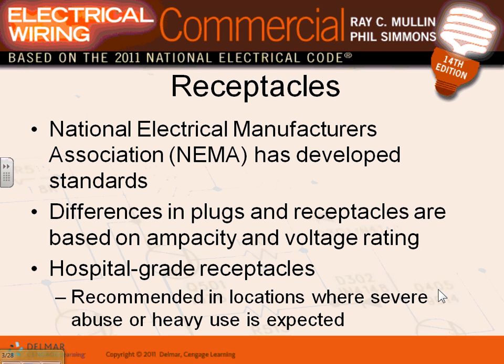Hospital grade receptacles, guys, are again, as I said, more robust. They're going to be very similar to this one, more robust. And most of the time, well, they changed in 2011, a lot of applications for hospital grade receptacles require an isolated grounding system. We'll talk about this one in a few seconds here.